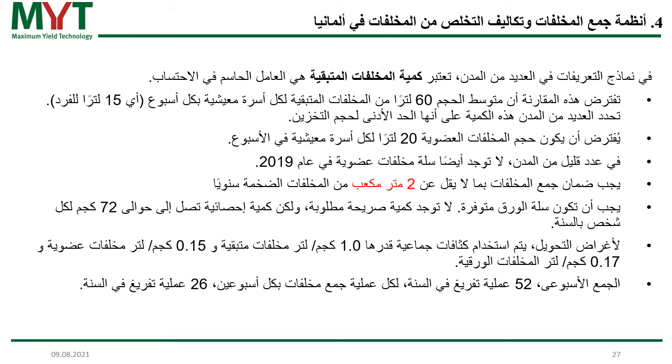But many cities specify the quantity as the minimum storage volume. So 60 liters is, this depends, it really depends. 60 liters is fine for some families, but others need more space. So the volume of the organic waste is assumed to be 20 liters per household per week.